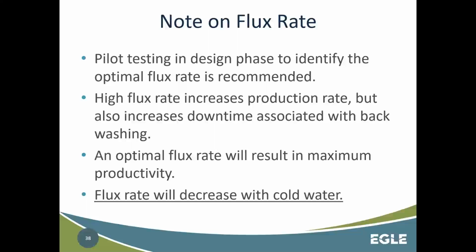Another key thing to note is your flux rates will decrease with cold water. You're not going to be able to get as much water through. However, from a regulatory standpoint, we are aware of that. And so when we have our membrane plants designed, we say you need to be able to meet your peak day demands with cold water.